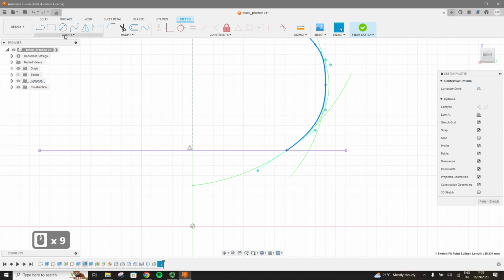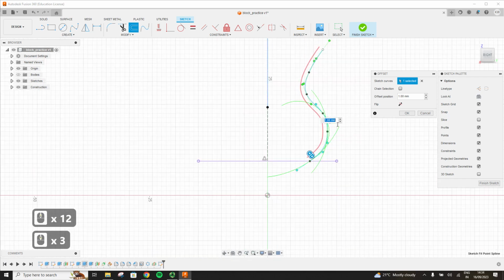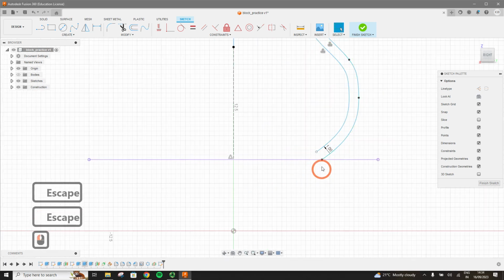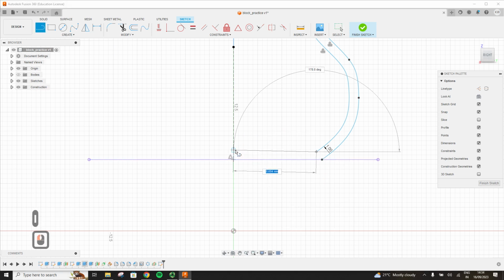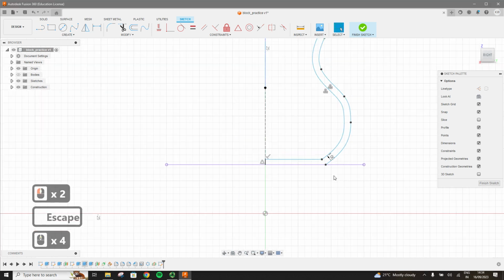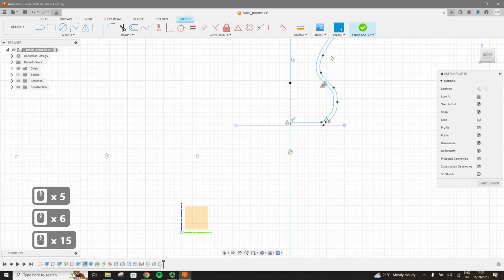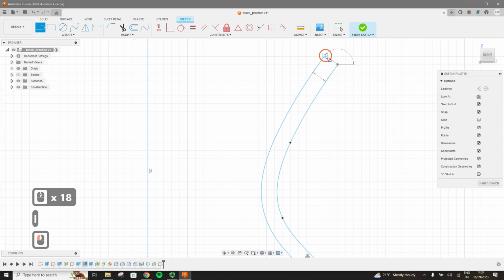Okay, so let's offset this because we want it to be a little bit thick. We just don't want it as a surface. And as soon as we offset, we can see that it has created a nice surface at 1 mm inside. Let's do OK. Let's try and close this, the bottom of the vase. So I'm just making a random shape essentially to show you the revolve command. And we can see that it's not a closed curve or a closed sketch. So let's close it like this.